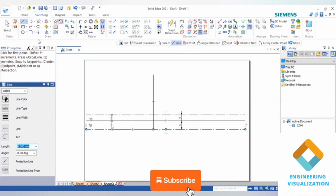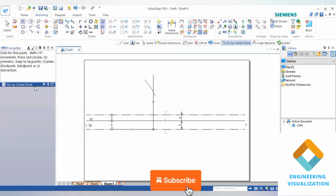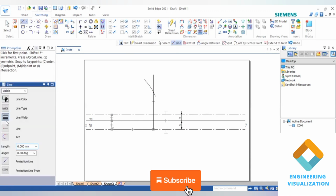Okay, go to arc by center, give true length 85 and cut the arc. Okay, because apparent length when it is rotated and projected we get the true length here. Okay, now you join from this end point to here.